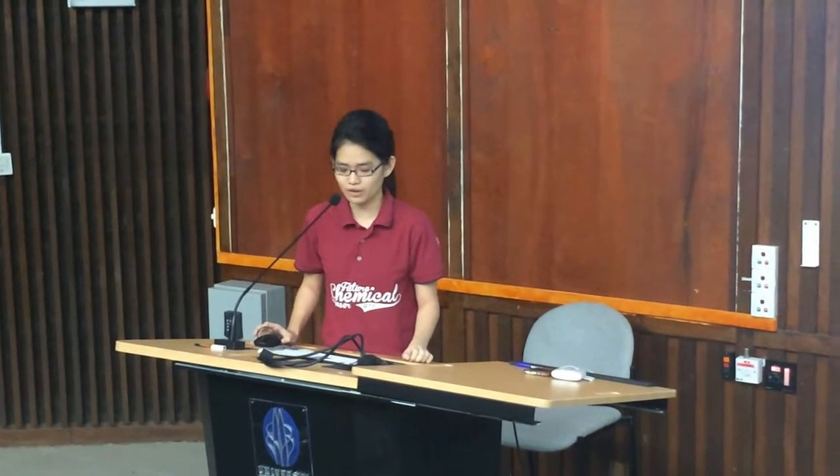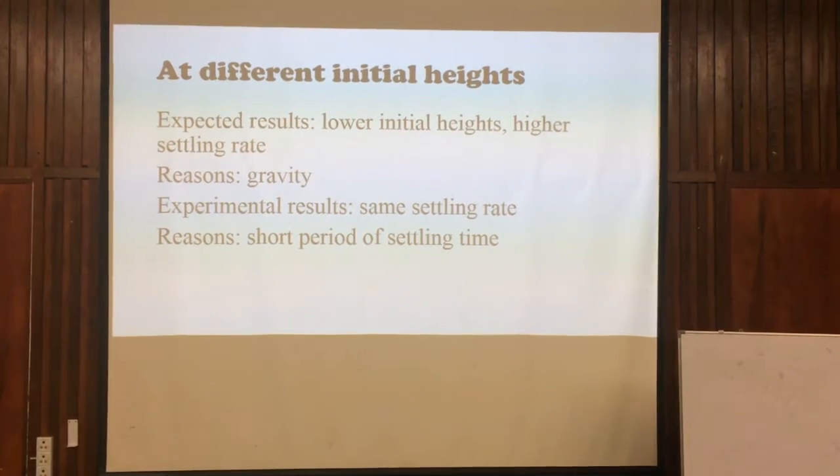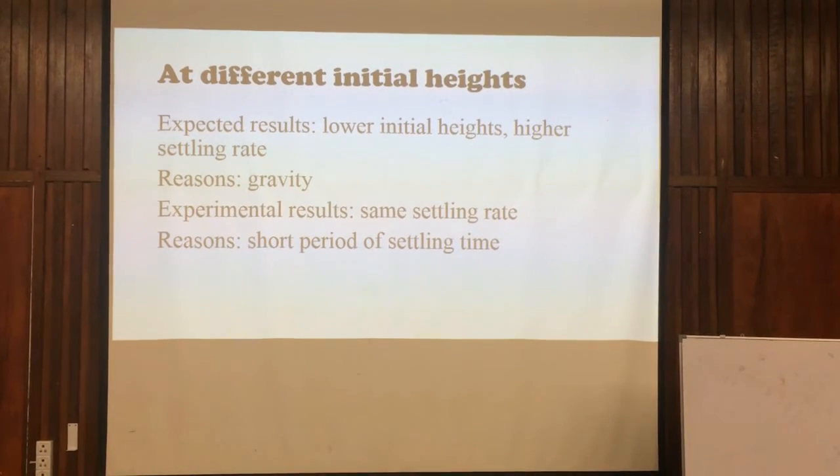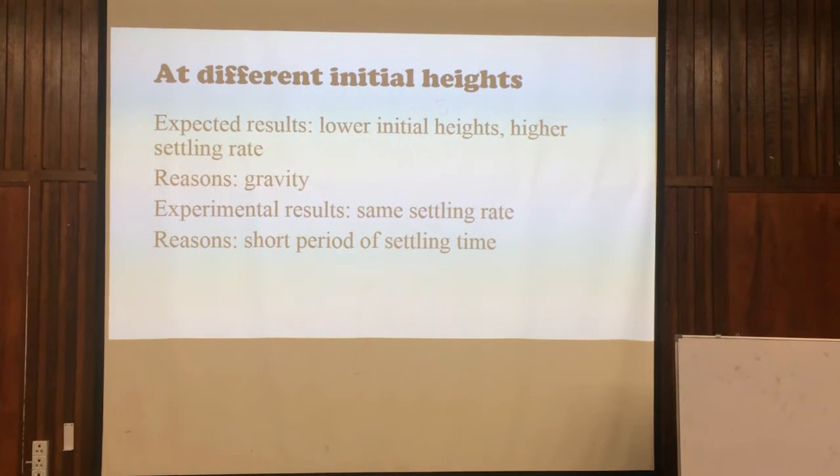For this experiment, we are dividing the experiment into 2 parts. Experiment A: we are going to study the relationship between the settling rate for suspension at different initial height and different concentration. And for experiment B, we are going to study the relationship between the settling rate and volume of flow current. For suspension at different initial heights but same concentration, cylinder 2, 4 and 5 are compared.